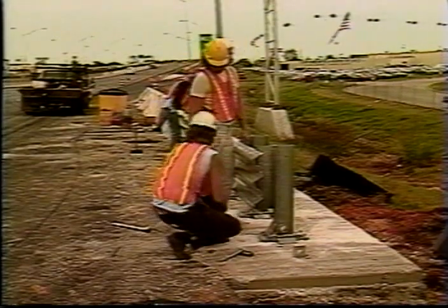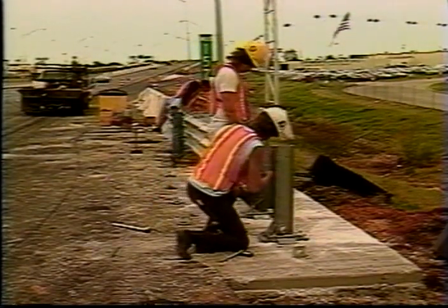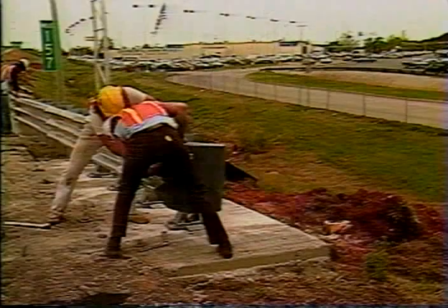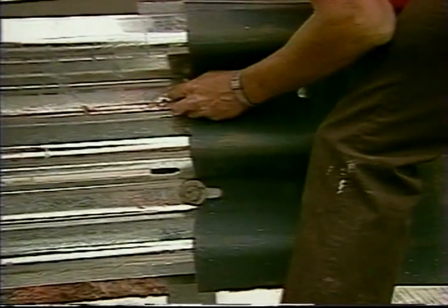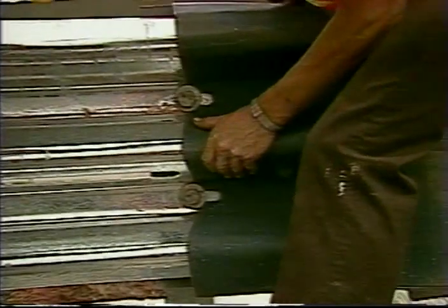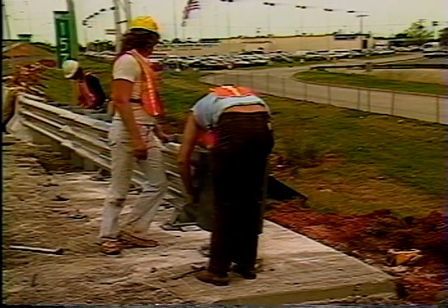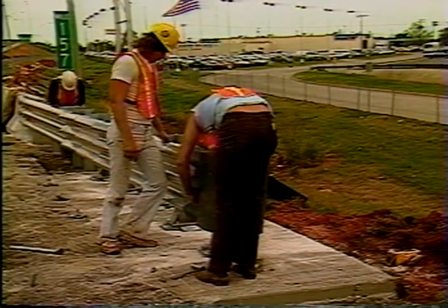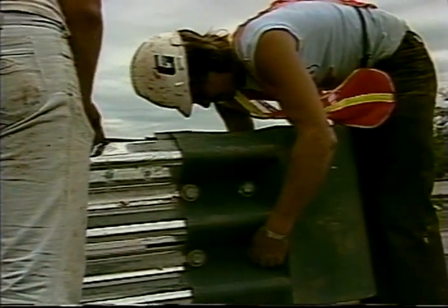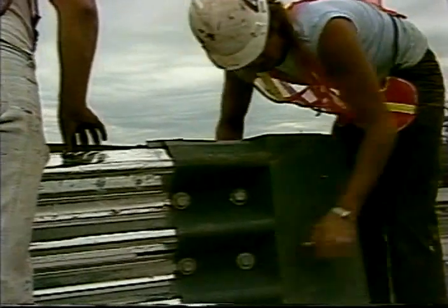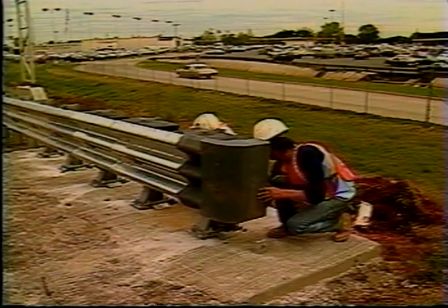At post 1, the 3/4 inch bolt assemblies must be left loose. The plastic bull nose is positioned over the panel but under the flat washer and bolt head before tightening the bolt assemblies. 2 bolts are also placed through the 2 remaining holes in the bull nose and through the 2 fender panel holes labeled G. The cable is now ready to be connected.